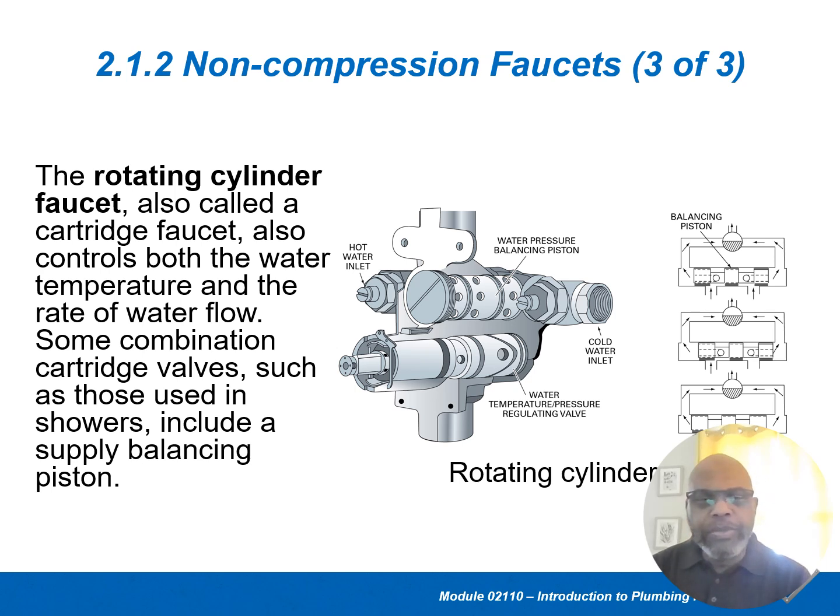Now, this particular one is for showers, and it's a cylinder inside of it. And they make the same thing, the cylinder, for certain faucets, also for sinks. And the cartridge, what's nice about it, you could just replace the whole cartridge pretty quickly compared to rebuilding a faucet with all those parts you see. And so all the parts are connected to this cartridge, but it's just easier to work with.